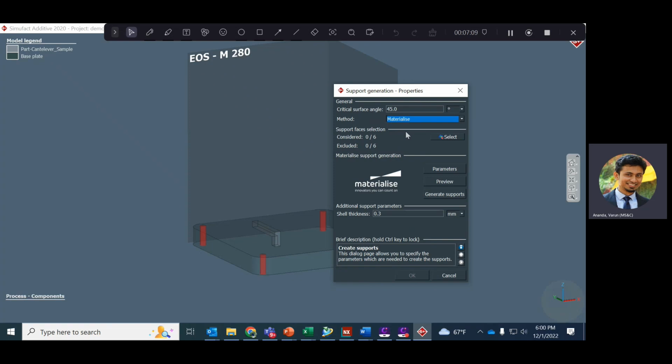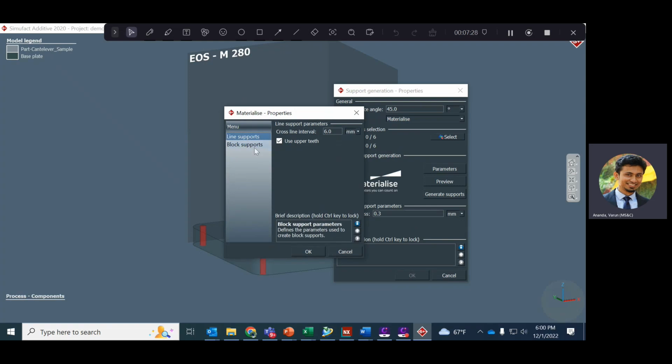Materialise Magics: we generate the STL file, import it in Materialise Magics software, generate the required support structures and create the slicing. The same environment is better for generating the FEA model as well.